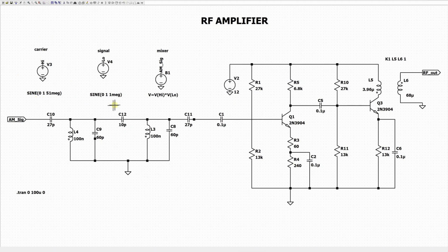using a carrier and the message signal. The carrier is at 50 MHz, and the message signal is at 1 MHz. The mix of the two signals gives us a signal similar to what the antenna should send to the RF amplifier if this circuit is implemented in hardware. So this is what we use as the input signal to this entire circuit.